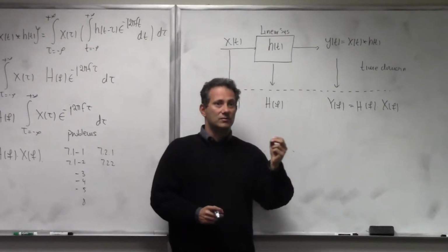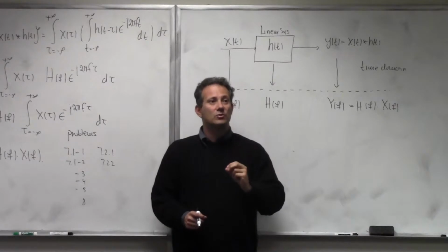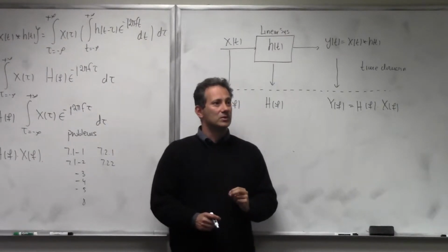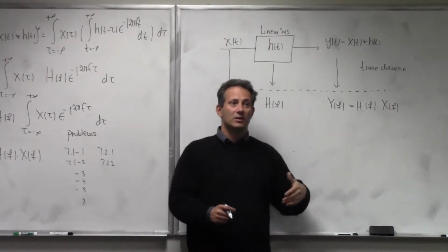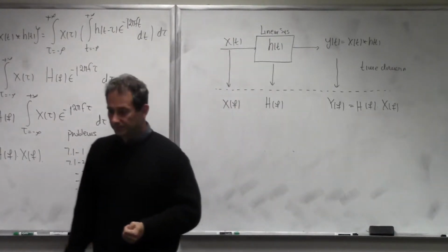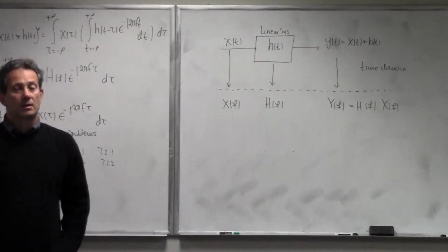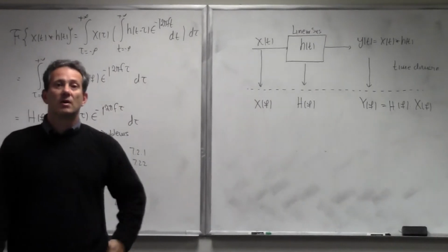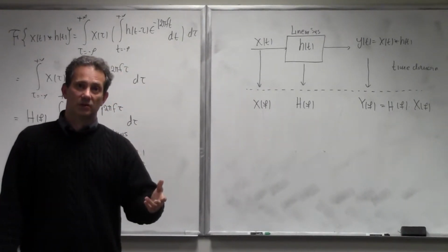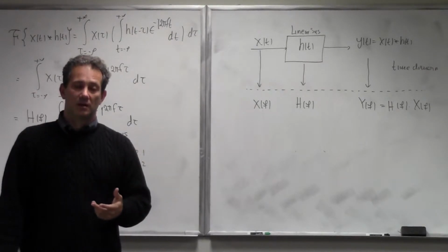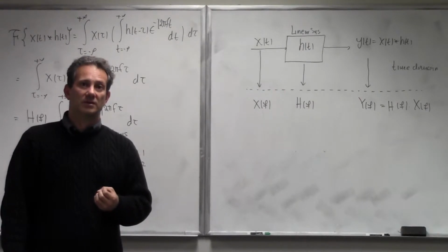From here, it is very apparent that a linear system cannot produce sinusoids of a different frequency. All it does is multiply and change the ones that are already there. No new ones can be produced. Can we take it as a test? Like we always do the frequency analysis of the output. This is one of the principal tests. We have what we call the single-tone test and the two-tone test. And these are the tests that are used to determine how linear your device is.